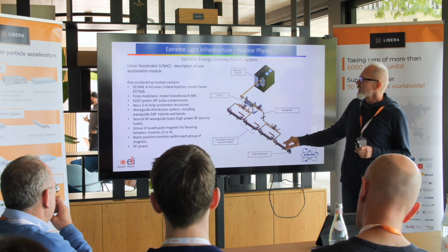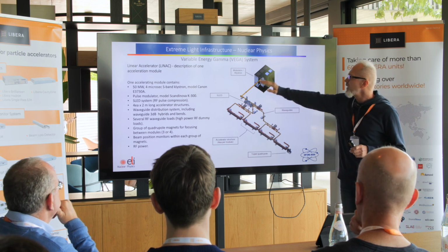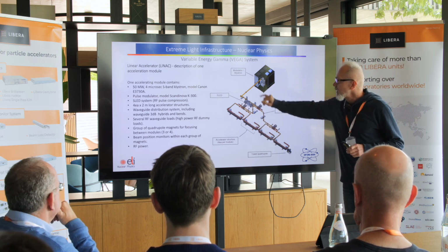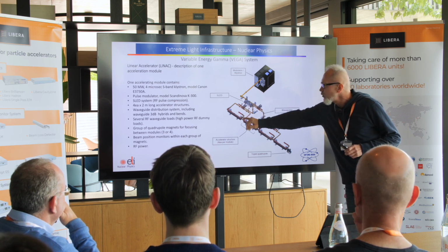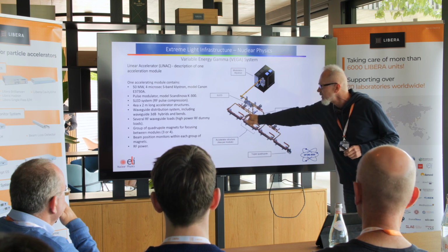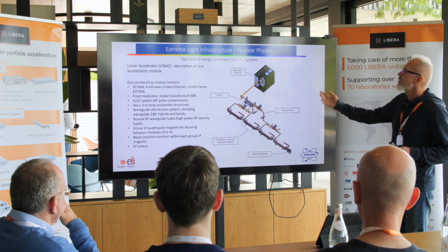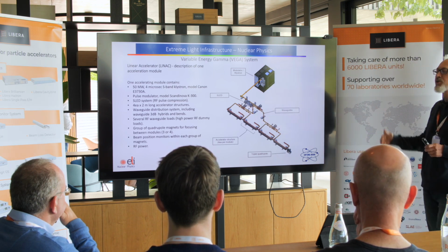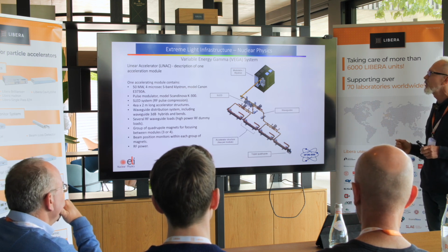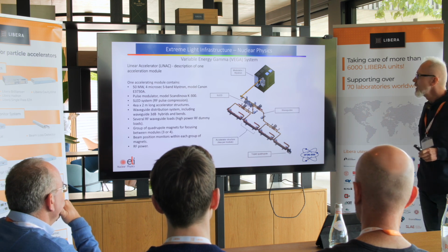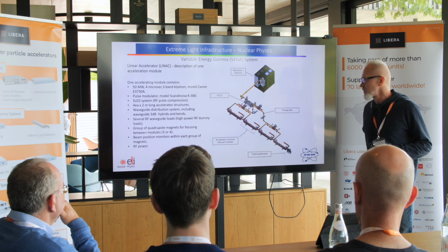So this pulse is going to be introduced in each structure. And after the pulse is introduced in each structure, it is circulating. And later on, after it is filled, it will be discharged through these RF loads, and this energy will be transformed into heat, which with the help of a cooling network will be maintained under control. So the working temperature of all equipment is 25 degrees Celsius.